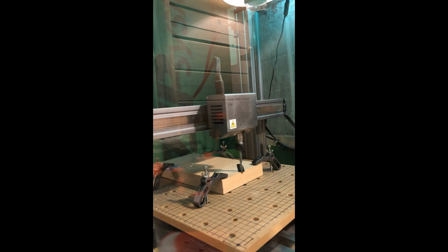Right there. Okay. Once I get to that point, I'm going to click, either in Luban, you can click the little Z box, and you click down at the second option, which is to set the 0 for the Z only. Or if you're on the actual Snapmaker itself, on the console, it has a button on the control panel there for the movement where you can just set the Z origin. So that's what you want to do, just the Z origin.